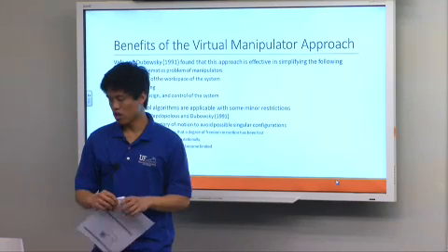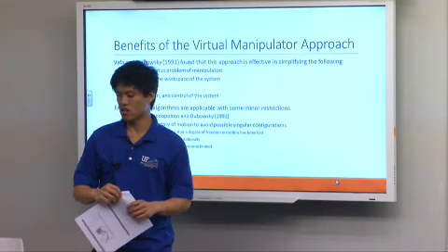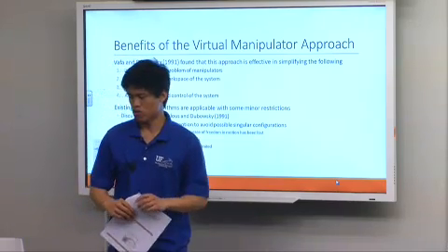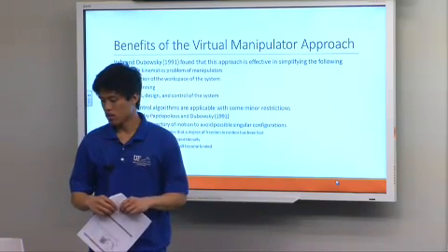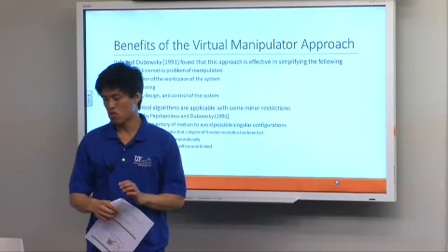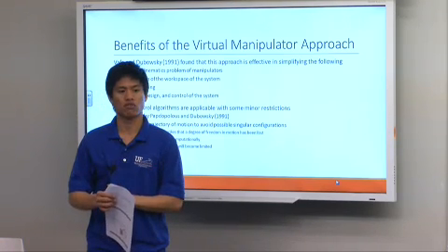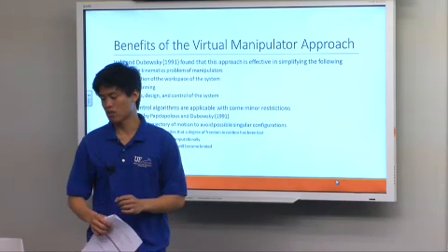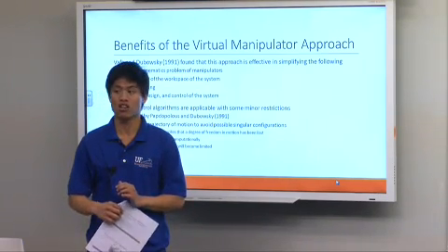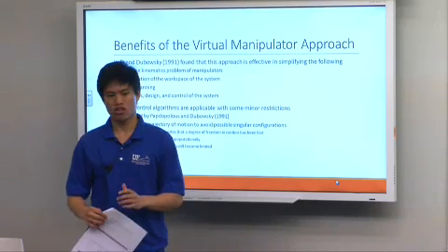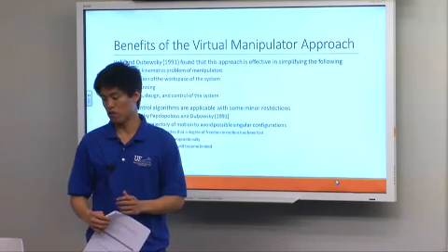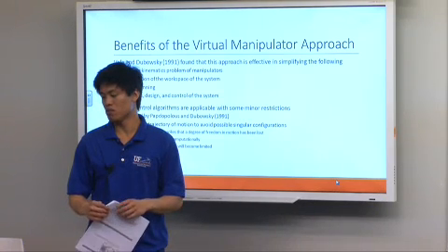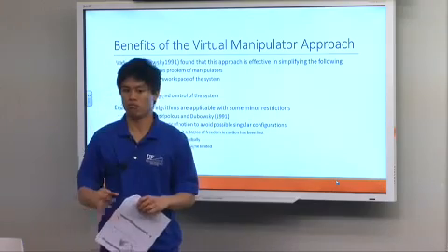And what Papadopoulos and Dubowski have found, the same professor but a different person at MIT, is that they can prepare the trajectory motion to avoid possible singular configurations. A singularity in robotics implies that a degree of freedom in motion is lost. This means that the control algorithm will fail computationally, and the workspace of the robotic arm will become limited. But they've been able to mitigate this problem.